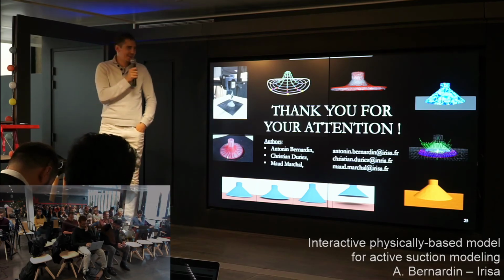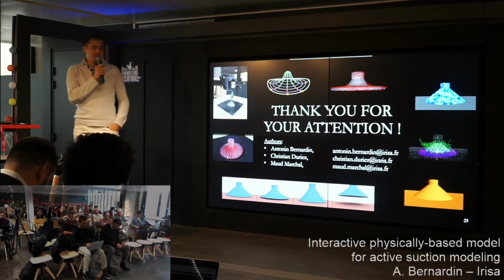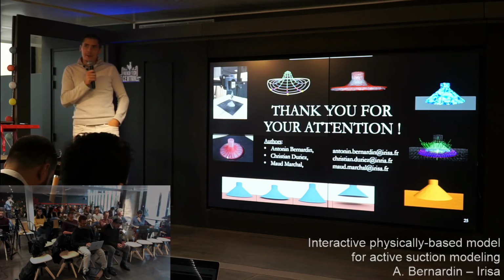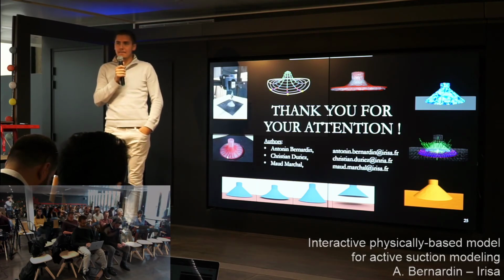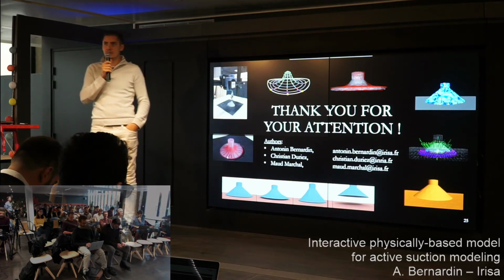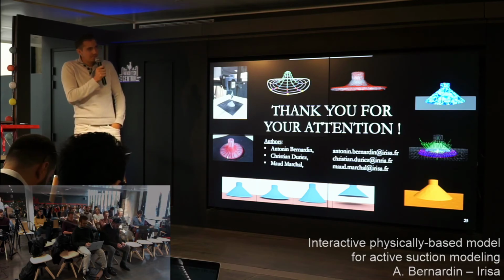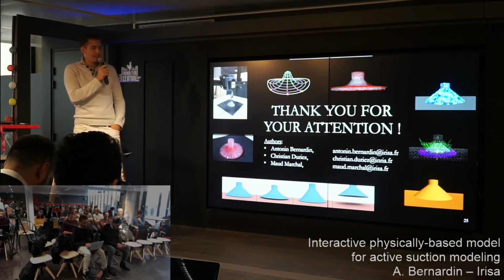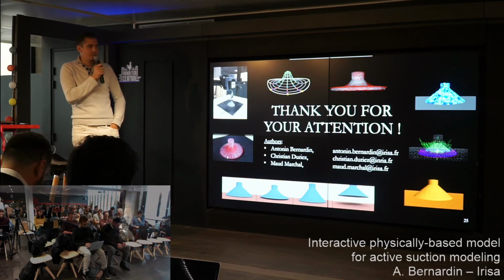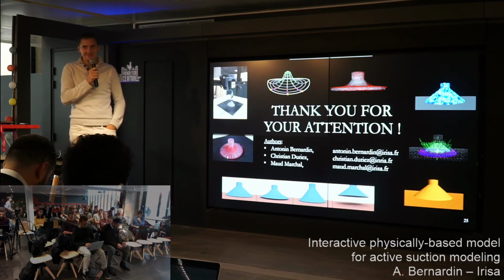It's quite challenging sometimes to mesh a thin surface using volumetric elements like tetrahedra, but apparently it's not so problematic in your case. Yeah, but of course we could improve it.